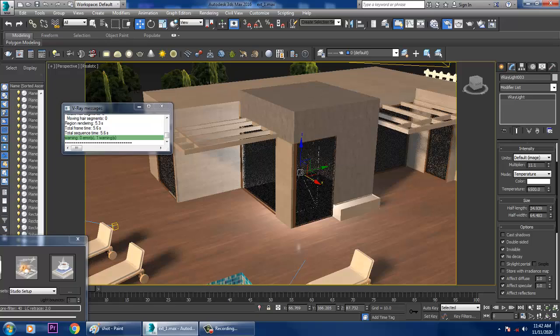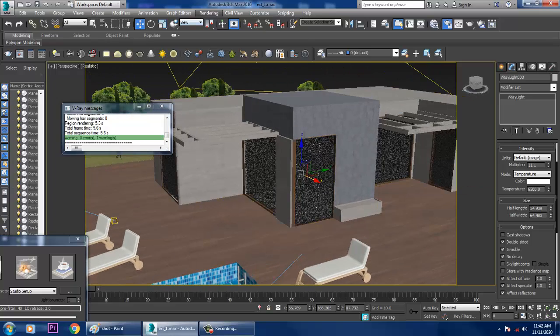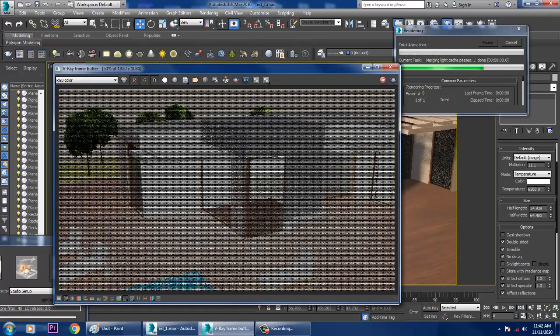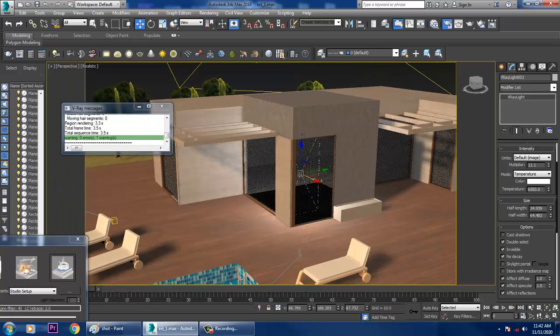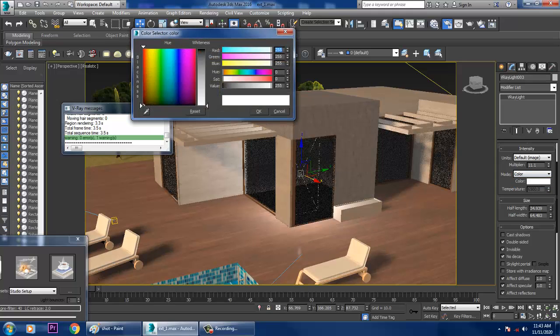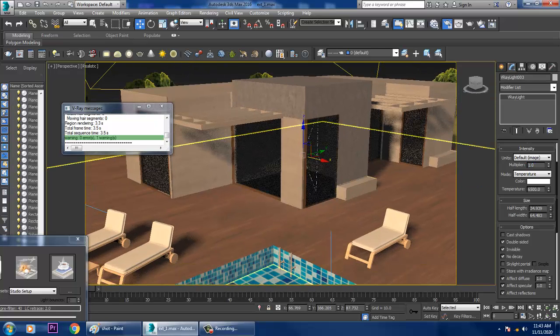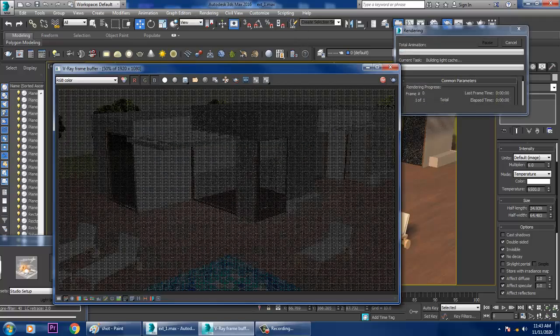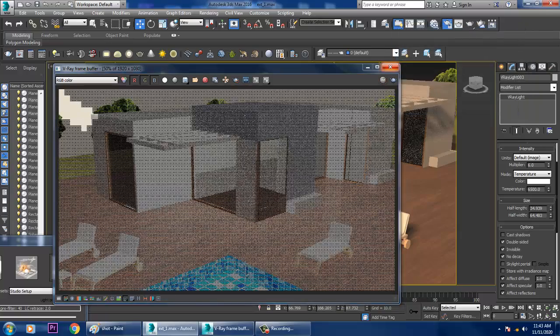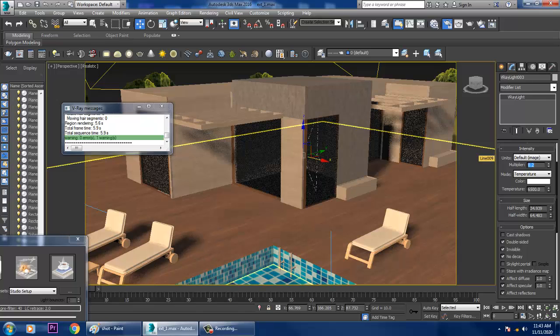You can show slight illumination from inside using those lights. Okay, but make sure the intensity is very low over here. So also with the intensity, if you're using a color over here, and a temperature 0.2, slight. Let's see the render, how it looks like. So definitely we need to reduce its light over here, 0.2, or you can go with that 0.8 over here.